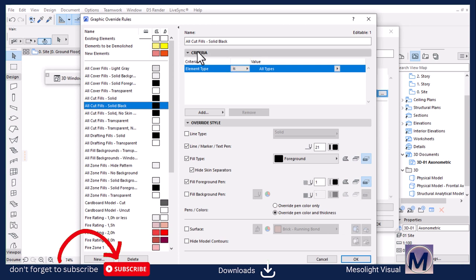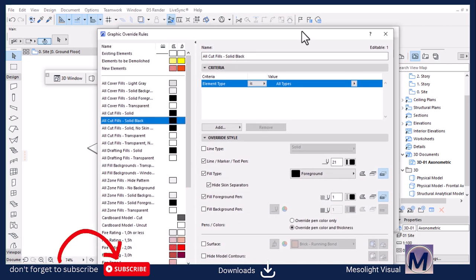What I'm going to do here, you see the criteria, it says the element type, and all types are being affected by this override style. These are the styles that are being overridden: the line type, the fill type, the foreground pen, and the pens. In this case, I don't want to affect the commercial plots.